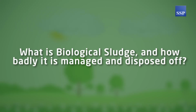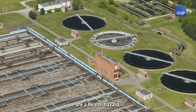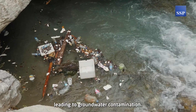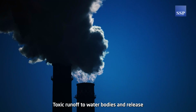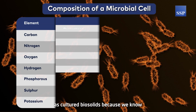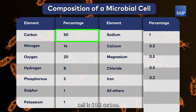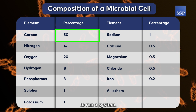What is biological sludge and how badly is it managed and disposed of? Sludge coming out of STPs is a health hazard, creating problems like infections and odor. Disposal issues lead to groundwater contamination, toxic runoff to water bodies, and release of greenhouse gases when dumped in the open. But we consider sludge as cultured biosolids because we know that the composition of a microbial cell is 50% carbon. This carbon can be used as a fuel source to run a system.